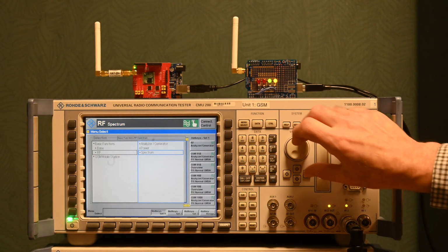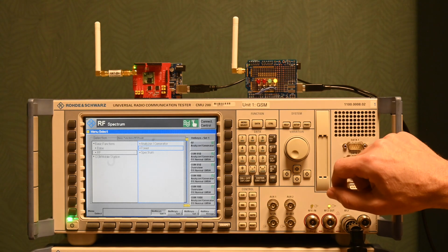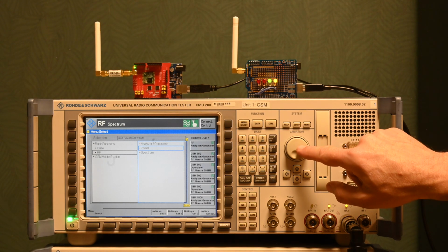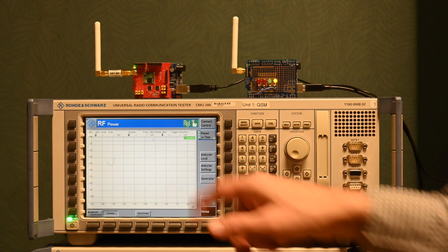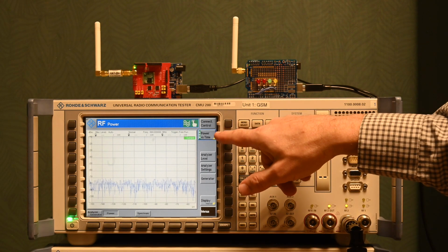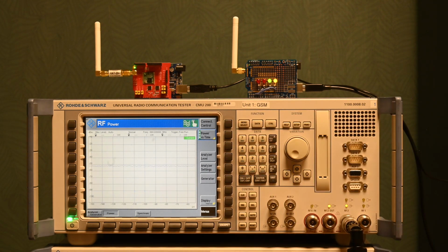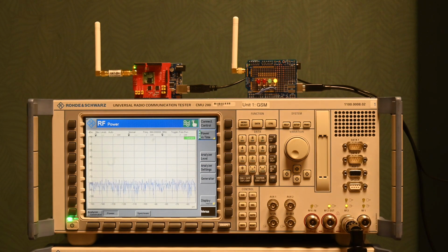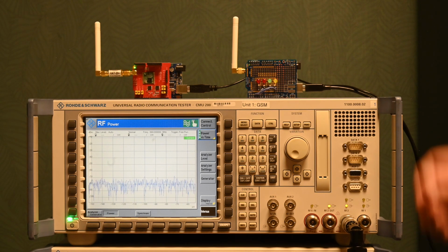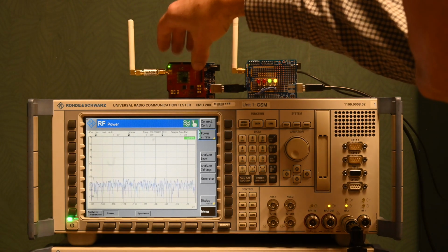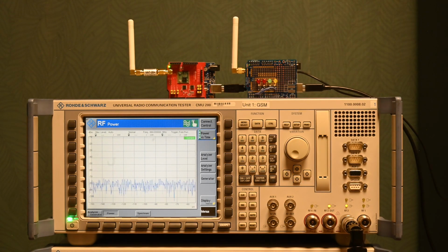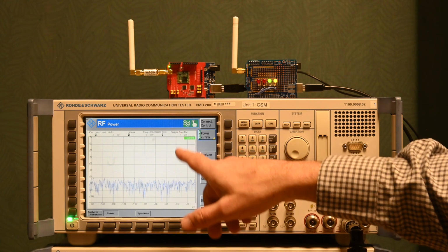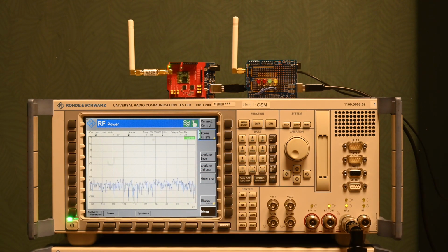So let's go back to the possibilities that the power analyzer over time offers here. So I'm going there now. This is the menu for it. We see that the application is running. And what we see here basically is a time domain and sometimes a jump to a higher power level. The thing is that it's not receiving my signal, maybe the attenuation is even so much that it doesn't take. There we go. Yeah. So we also kind of see two different power levels. But of course we would like to study the burst a little bit more in detail.